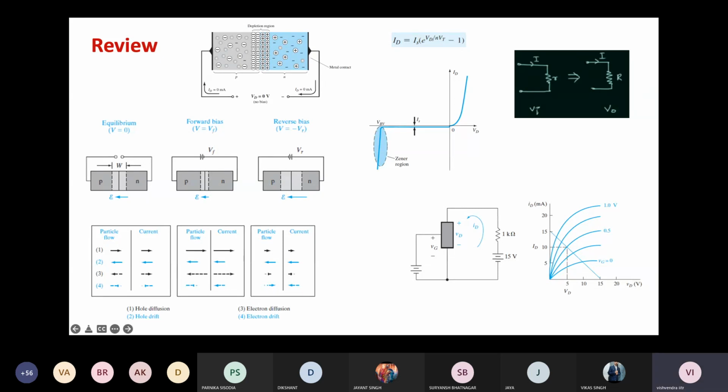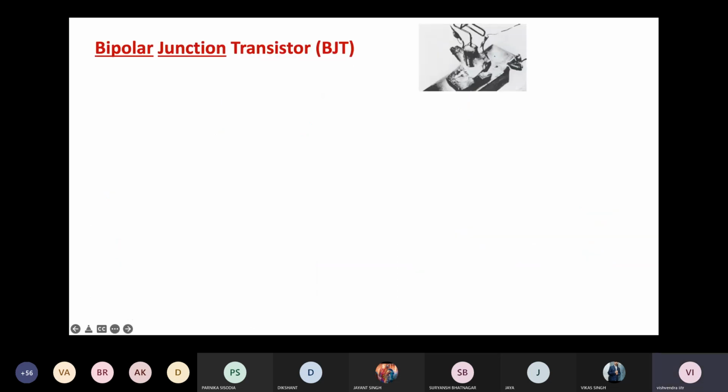So there are these two ways to implement the transistor nowadays, and this is essentially BJT and this is the MOSFET. And what is a transistor? Transistor is a device through which we can achieve switching and amplification. So please remember that. A transistor is a three-terminal device in which switching and amplification can be achieved, and one of the terminals can control the current across the two other terminals. Any doubt, anything that you would like me to repeat till now?